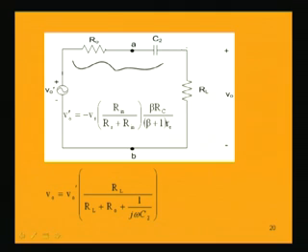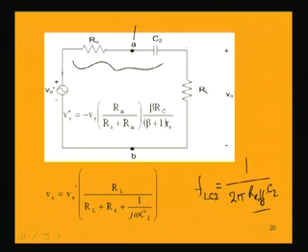So, that is a very simple analysis, we can straightforward find out, and that is what we can get directly: the lower cutoff frequency, which is equal to 1 by 2 pi into effective resistance across this capacitance into the capacitance. Now, what is the effective resistance across the capacitance? To find that, we have to look into the circuit from that capacitance, that means from this portion of the circuit we will be looking into, making this capacitance open. What will be the effective resistance?